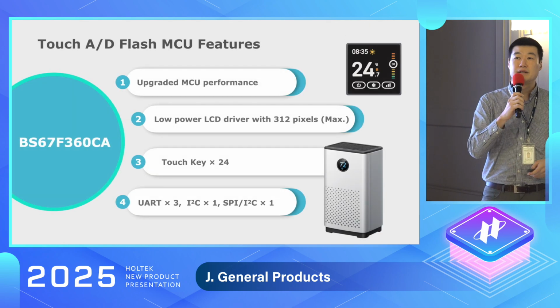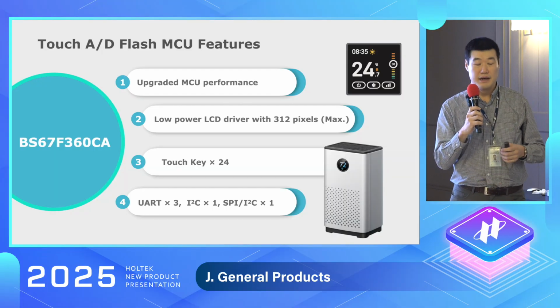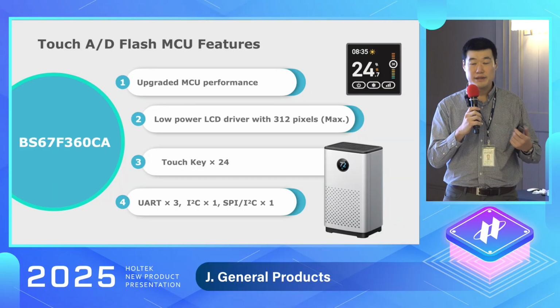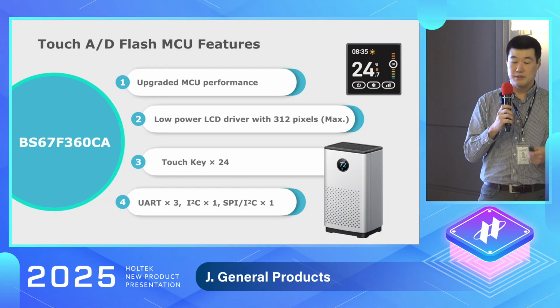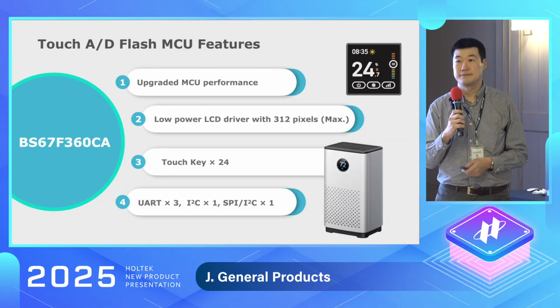Oh, let's talk about the features. It has upgraded MCU performance. The LCD driver can support a maximum of 312 pixels, up to 24 touch keys, and it supports UART, I2C, and SPI.